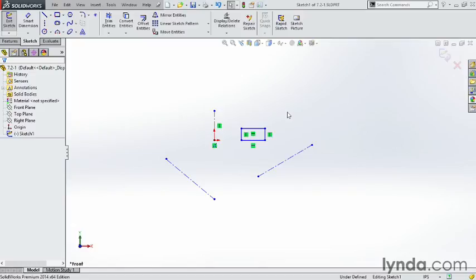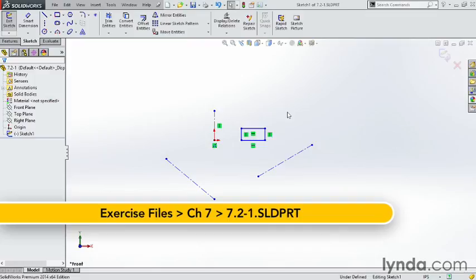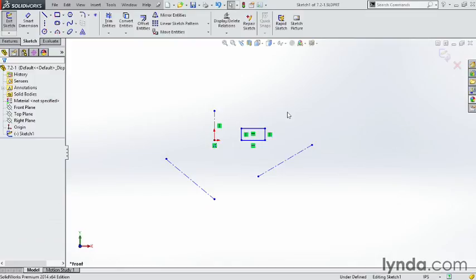Much like the extrude command, the revolve feature creates geometry from a sketch. However, the revolve requires one more ingredient, the axis of rotation. Once you have a sketch, the next element is the center line, axis or internal line of the sketch.